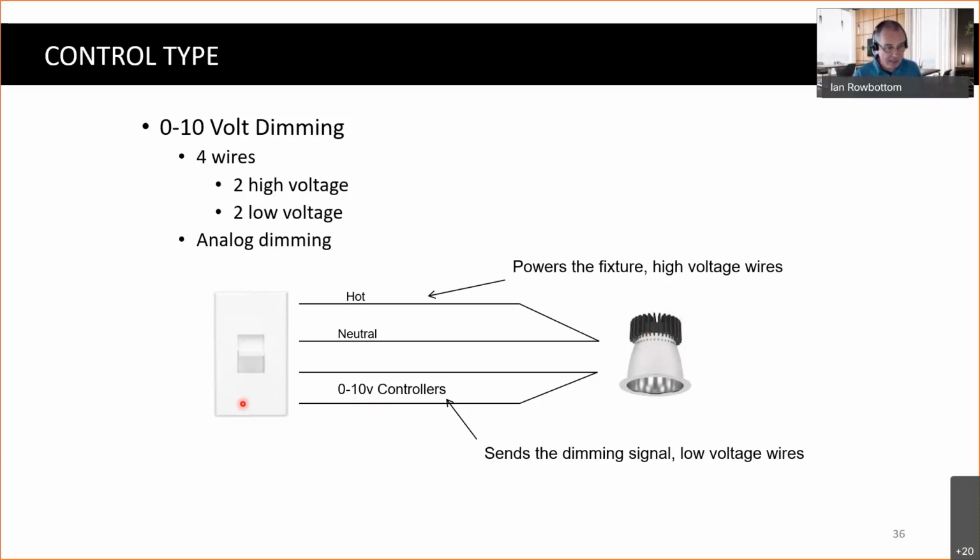There is another standard called the ANSI standard, which comes from the theatrical world that says, no, wait a minute. The dimmer shall source the current and the LED shall sink the current. Obviously, if you have the wrong dimmer with the wrong driver, the two are incompatible.